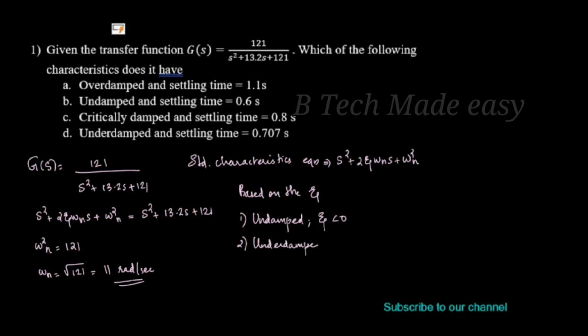For an underdamped system, the value of zeta lies between 0 and 1, that is 0 < ζ < 1. And third type is critically damped system. For a critically damped system, the value of zeta is equal to 1. And the last type is overdamped system. For an overdamped system, the value of zeta will be greater than 1. These are the system classifications based on the value of damping ratio.